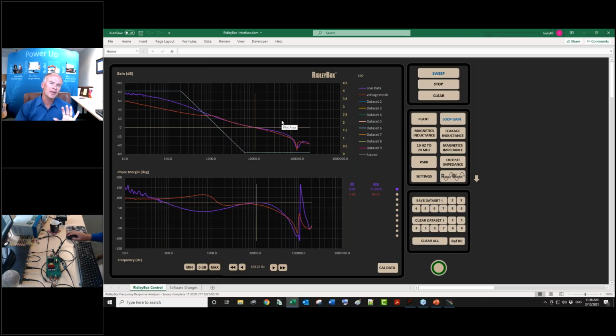Some people think that, well, the loop is the hard thing to do. I don't want to do that. I want to do impedance. I want to do PSRR. Okay, they are much harder to make and get accurate. You can do it on a little play converter, a little 5-watt buck converter, sure. Measuring impedance is easy. We'll do it on this converter, which is 60 watts, but you're going to see it's always noisier.